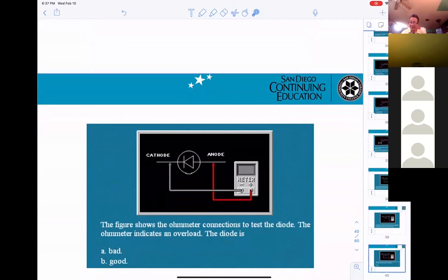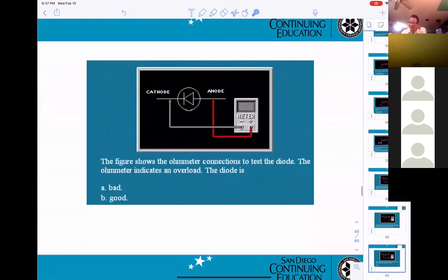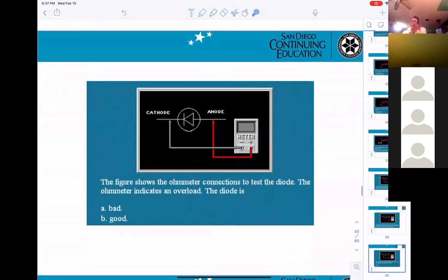So approximately how many ohms, Mr. Pham? How high? It's hard to say. You have to connect it and measure the resistance. You connect positive and negative first, then you reverse it. The ratio has to be very high, maybe about 1,000. Normally now, you don't have to do that. The meter already has a symbol for measuring, to test the diode.